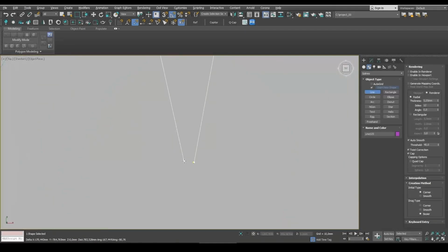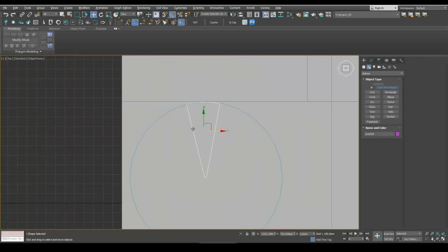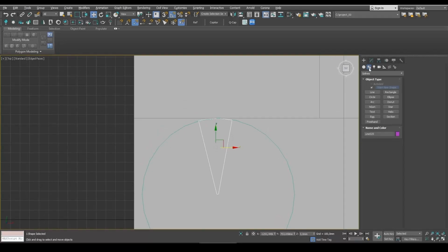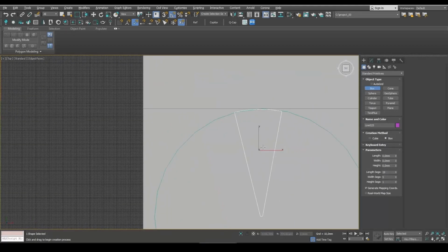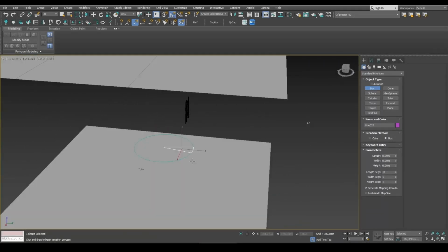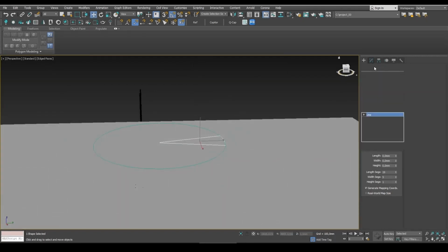Now, it's important to say that there are certain width requirements for steps, and we must stick to them. Here the depth is about 30 centimeters, it meets the requirements. The height of each step is 15 centimeters. Now, of course, steps come in different sizes. Now, let's see how much it is. That's 300, so that's good. That's within the required range.